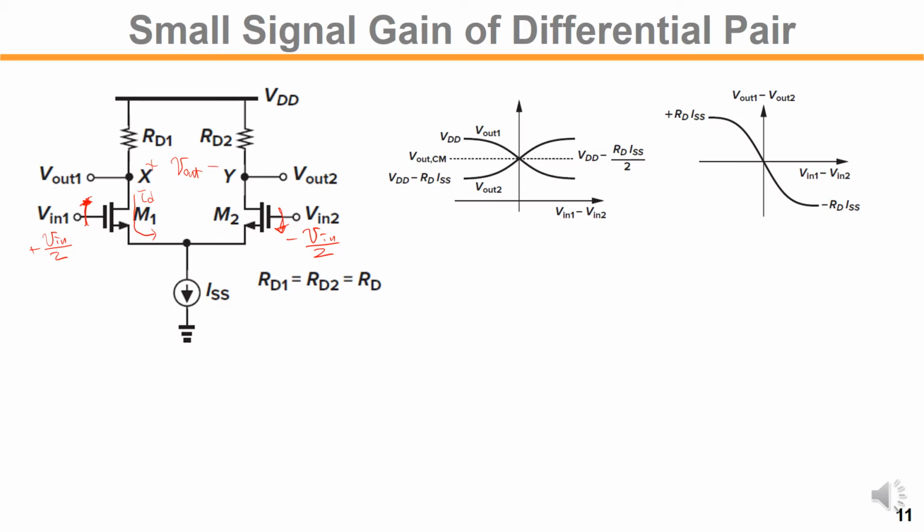That is represented by the current variation through the drain and source in the opposite direction. Since there is the tail current source shown here, there's no current variation. So in AC small signal analysis, there's no current variation, meaning it is an open circuit in small signal analysis.